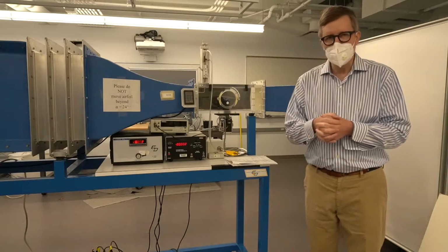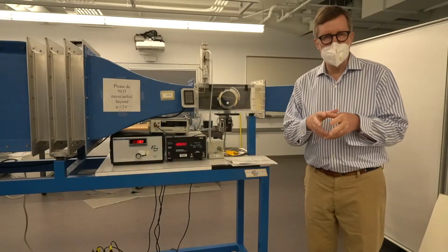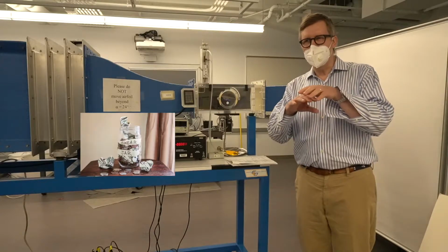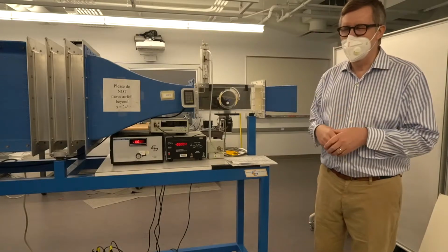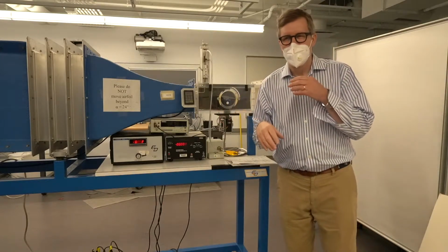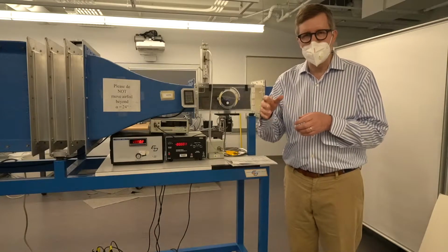The airfoil that we've got is called a NACA, N-A-C-A 0012, and the 00 tells you that there's no... what is it called when the airfoil has no camber? Camber, yeah. Thank you very much. It's symmetric. Sorry about that, everybody. It's a symmetric airfoil, so the shape on the top is the same as the shape underneath.